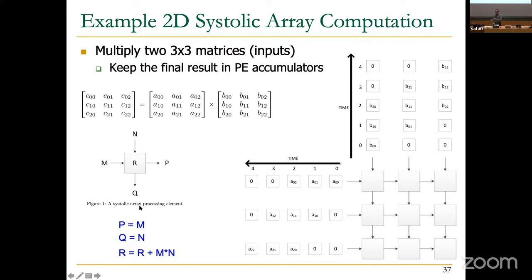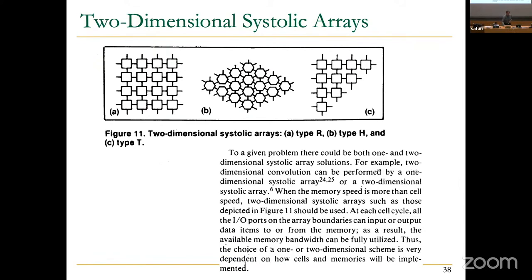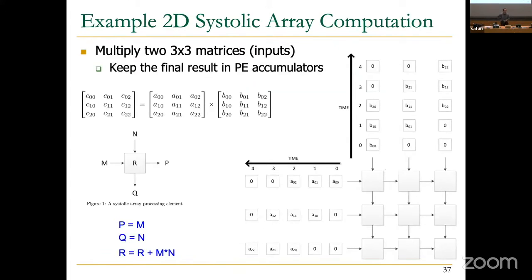So there are many, many interesting variations in the end. As long as you know how data needs to flow and how a systolic array operates, it's very easy. Okay, so I'll give you more examples. This is essentially what Google has built, basically. They have built a matrix vector unit, or matrix unit, as they say, and we're going to take a look at that. And this is very powerful in their systems.